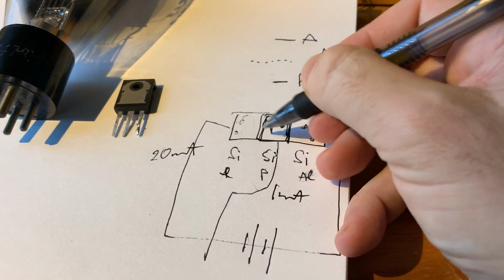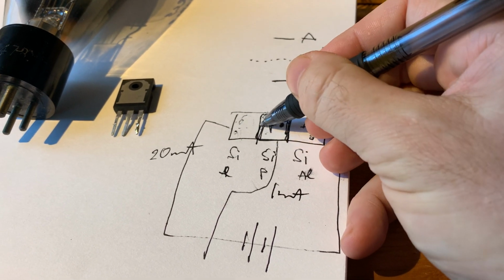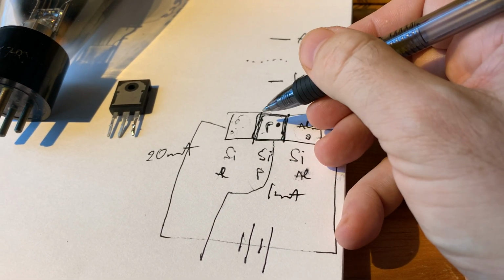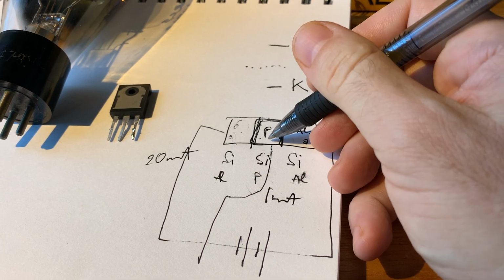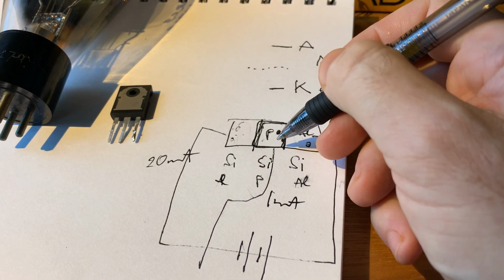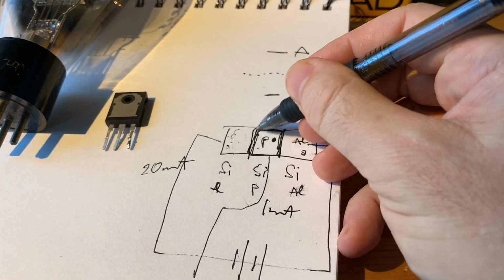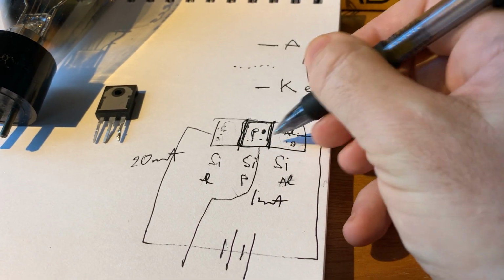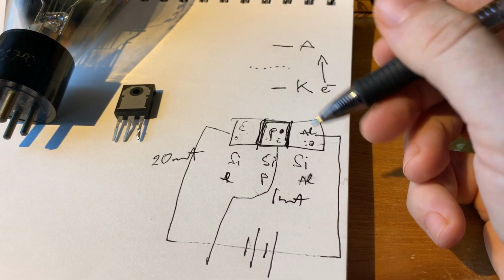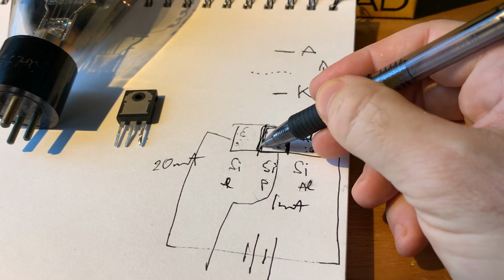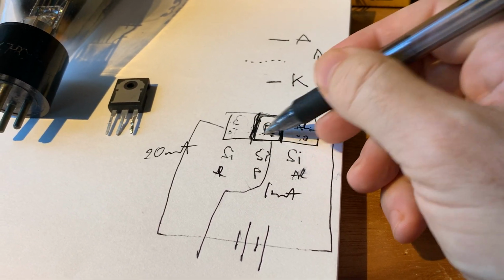This control element is physically connected, and the boundary, the interface between these two electrodes, is a chemical interface, and it changes depending on the voltage applied to the control electrode. Whenever you change your signal, the properties of that boundary change. So we've got a limitation there: there's an electrochemical reaction happening between these elements.